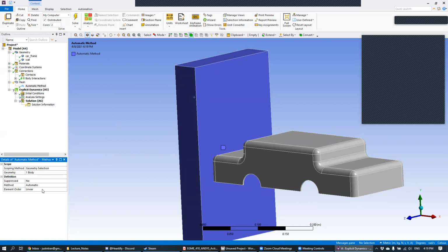But one thing that we do need to do for this simulation, because this is a dynamic simulation, is change the element order to linear. Which is counterproductive to everything that we've been discussing since Tuesday, where even though this is a dynamic simulation, it's still structural in its nature, because the car is going to structurally deform. If you remember what we talked about on Tuesday, we talked about the issue of shear locking, which is a dangerous thing, where if you have linear finite elements, then you could have the whole system just kind of lock up, right? And so that concern is still there.